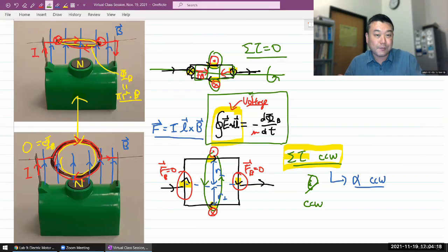And at the same time, if you want the motor to spin faster, okay, apply a higher voltage, and then it'll be able to spin faster. And this is again why it's dangerous to just stop the motor, because if you just stop the motor, the amount of current that can flow through the coils is no longer limited by something other than resistance of the wire.